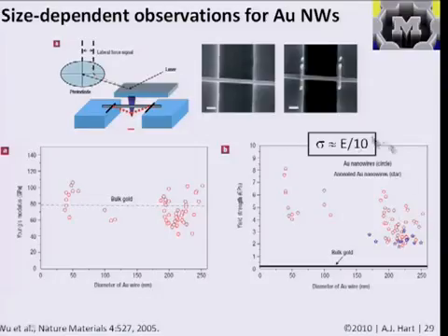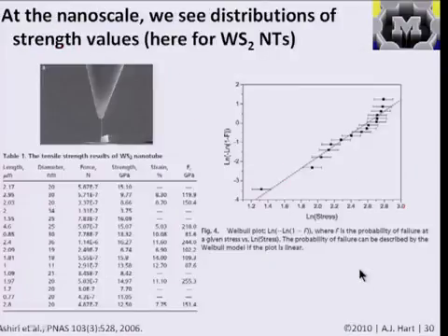And the other interesting thing to me here is that we see the material approaching this limit that I proposed of strength being about the Young's modulus divided by 10. So here we can say that this wire is yielding by actually deforming the bonds until they fail. And our strength is not limited by other aspects of organization of the material. And it's certainly a big difference between this scale and the macro scale.